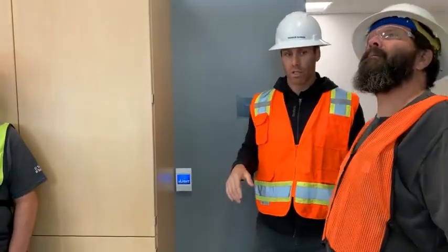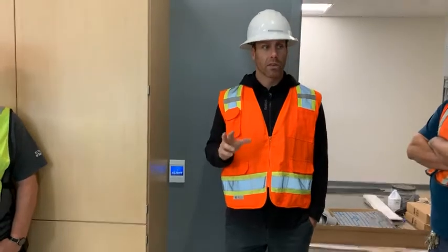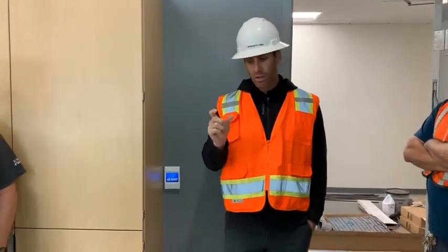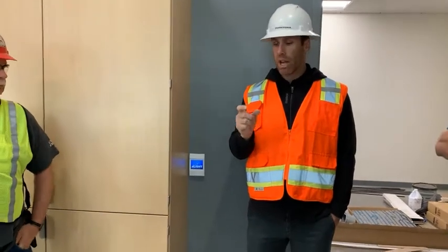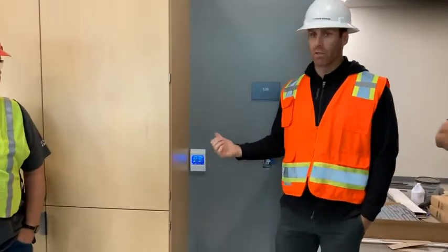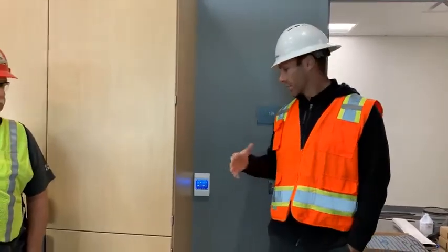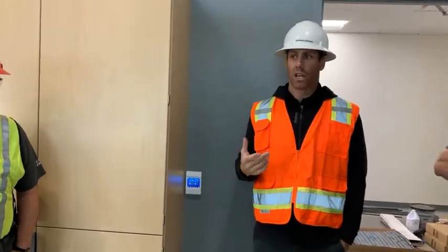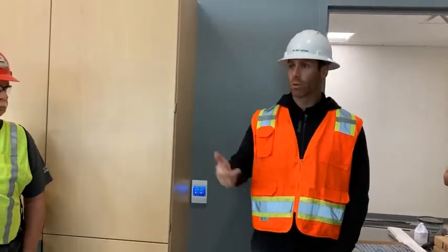With our switches, you're going to run into a number of different styles. The rooms have what's called a single pole switch. It's literally just all of our devices fit in a single gang box, but that one's just on, off, raise, lower. Here what we have is the nLight GFX. Okay. This one's used not necessarily just for aesthetics, but because it can do up to 16 channels. When we say channels, think like switch legs. Like you could literally, like if you had 16 single pole switches.